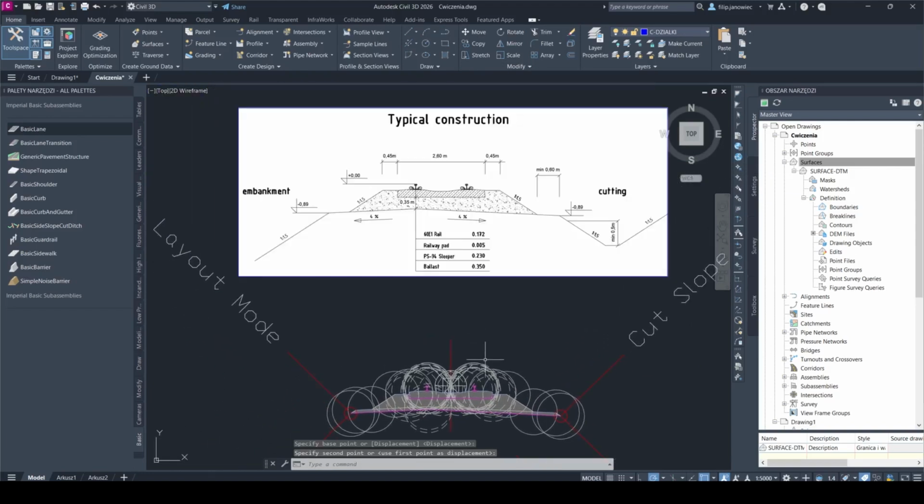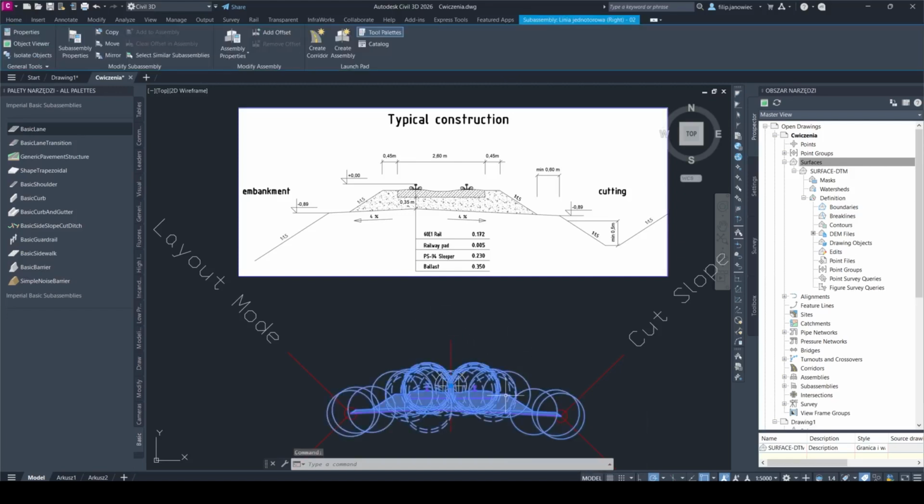Okay, so as you may see, we must have the 45 centimeters length till our concrete sleepers. We must have the track bed shoulder, which is 60 centimeters. Our depth, measuring from the bottom part of the sleepers to our subconstruction, must be 35 centimeters, and our slope must be around 3 to 5%. So to do this, we must click our sub-assembly.